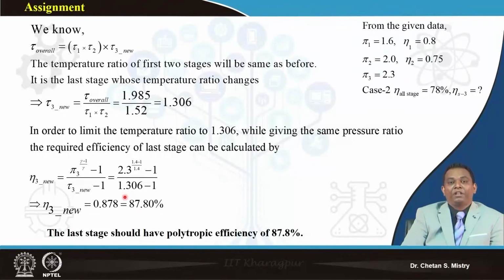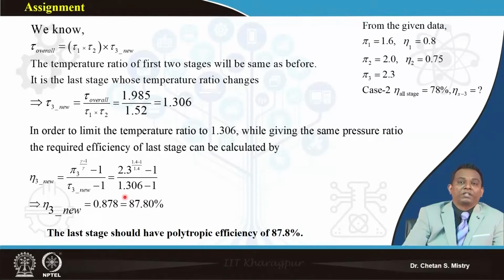And again, let me repeat what I was discussing: whenever you are having a conversation with a salesperson, or maybe those who are supplying you a compressor or an engine, when they are claiming some numbers in terms of efficiency, be careful. As and when required, just inquire and check whether they are talking of the overall efficiency of the compressor or the polytropic efficiency of the compressor. So when we move ahead with our design part, we will be taking care of polytropic efficiencies.